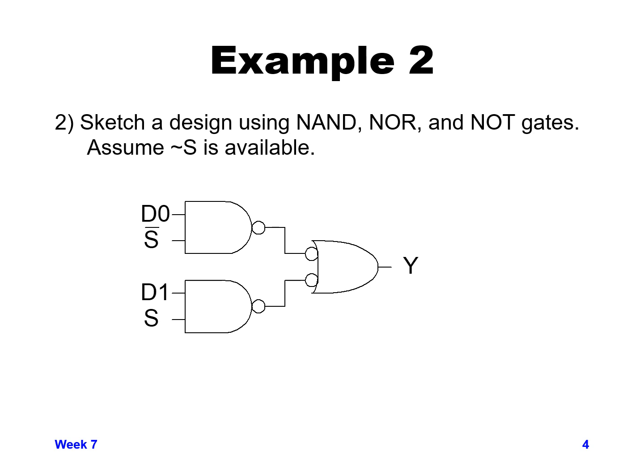So we're using two NAND gates followed by a NAND gate, but we're showing it as its alternative logic of NOT OR. And effectively, the bubble at the output of the NAND gate and the bubble at the input of the NOT OR kind of offset each other. So this is equivalent to AND gate followed by OR gate.